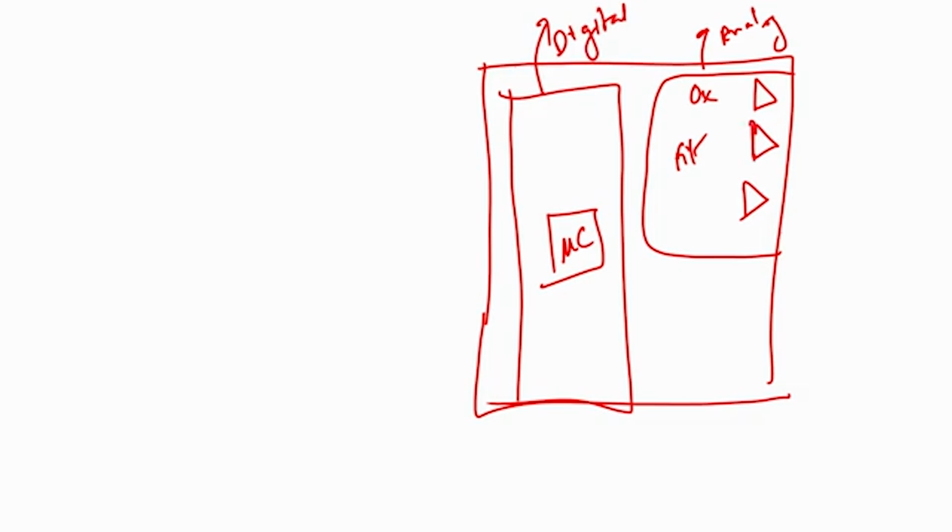Now if you do a hard coded design, your amplifications will be fixed. So during the time of bringing up your PCB, this will become your mixed signal PCB. During bring-up of a PCB, you will be faced with either desoldering the resistors that you have used for your amplification, finding new resistors and soldering them back to change your amplification, or you can use this beautiful circuit to control the gain digitally.